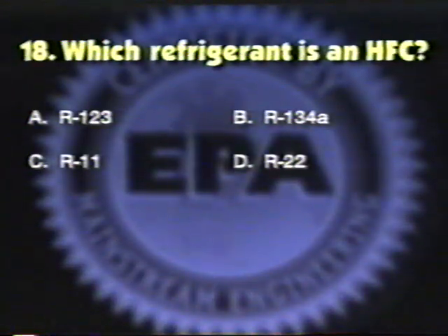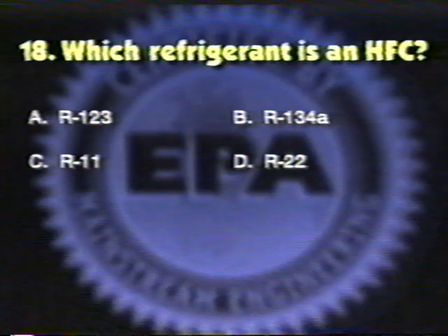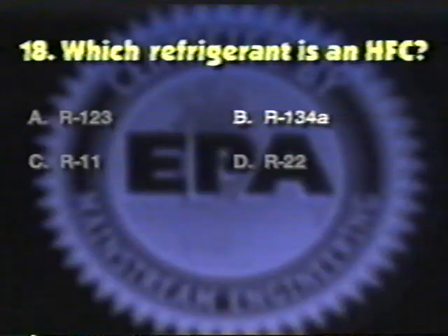Which refrigerant is an HFC? A. R123, B. R134A, C. R11, D. R22. The answer is B. R134A. Be sure to know which refrigerants are HFCs. R123 and R22 are HCFCs, and R11 is a CFC.